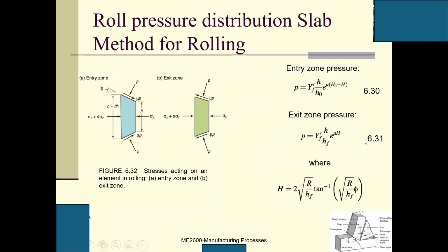Neutral axis, when we solve the beam problem, when we have a bending problem for the beam. Neutral axis means that along this axis, before and after you bend it, the length does not change. Here, neutral point is not analogous, but it's kind of similar.